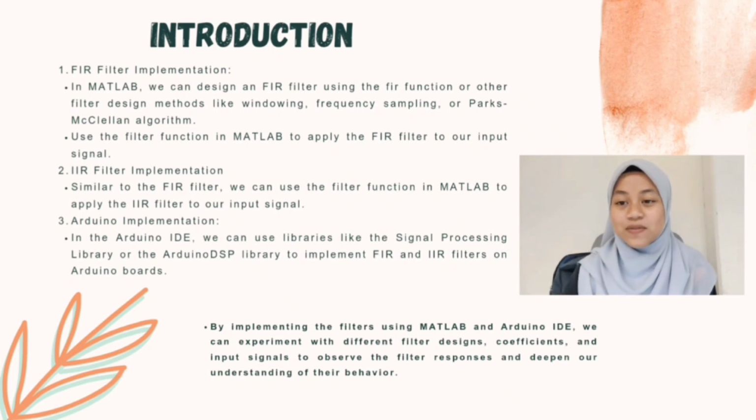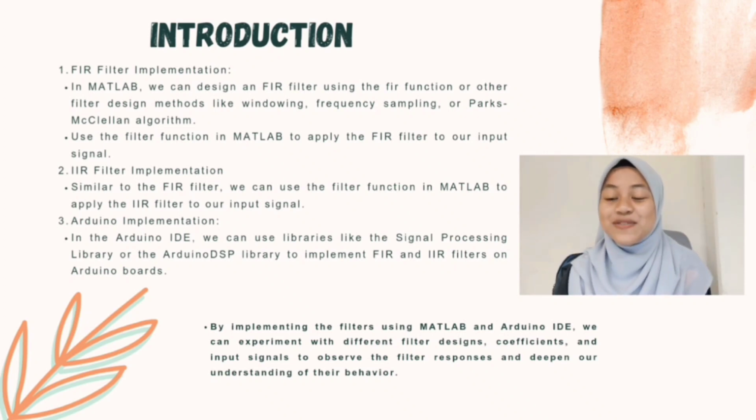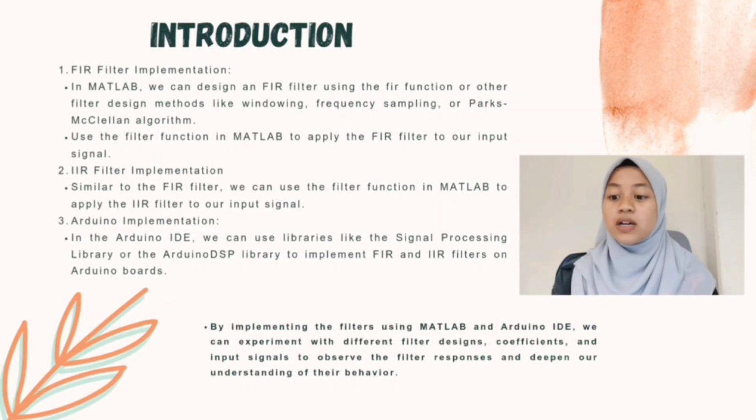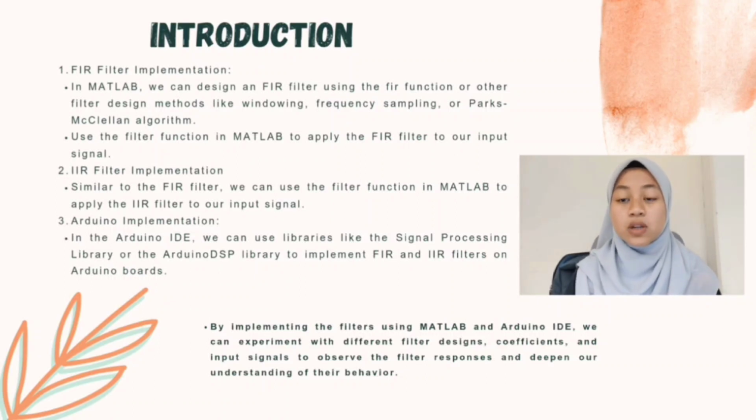I want to explain about finite impulse response and infinite impulse response. For finite impulse response, filter implementation is in MATLAB. We can design an FIR filter using the fir1 function or other filter design methods like windowing, frequency sampling, and others. So this will give us the filter coefficients